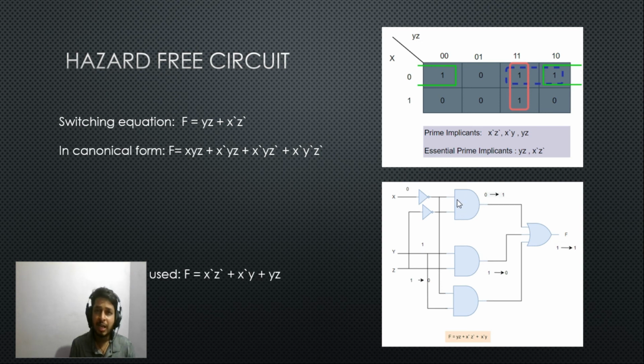We call them timing arcs in static timing analysis. Let's not go too deep into that, but anyway, the timing arcs, or the speed of this gate, may not be the same for all the gates. Okay, because of that difference in speed of the gates, this gate may be faster than this gate. This situation of dynamic hazard can always happen. Okay, so this is exactly the same situation. The output goes momentarily to another state, but it's because of some other reason. It's because of the transition times of the cells itself that there is a difference.